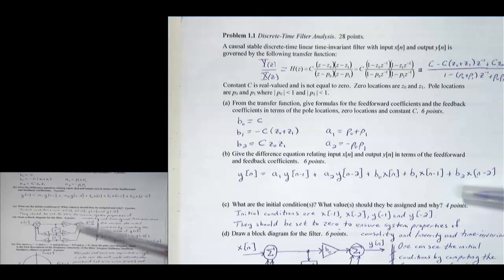You can also, if you do the block diagram form that's direct form, you'll see the initial conditions because every initial condition corresponds to one delay block. There are lots of ways you can get the initial conditions. Block diagram, I did the one delay line form down the middle instead of the two delay line. Either one's fine. You have a delay line along the inputs, a delay line along the outputs. We just have to have feedback here for an IIR filter.